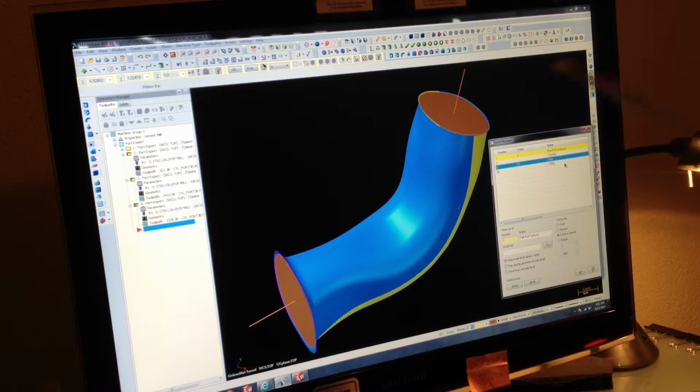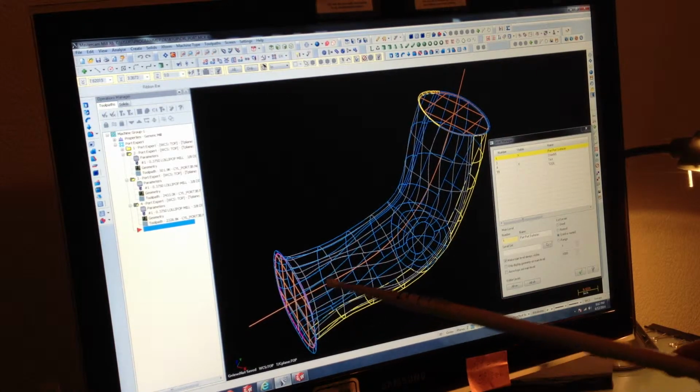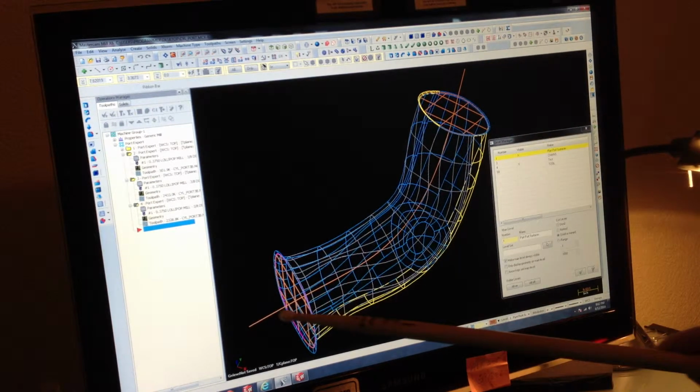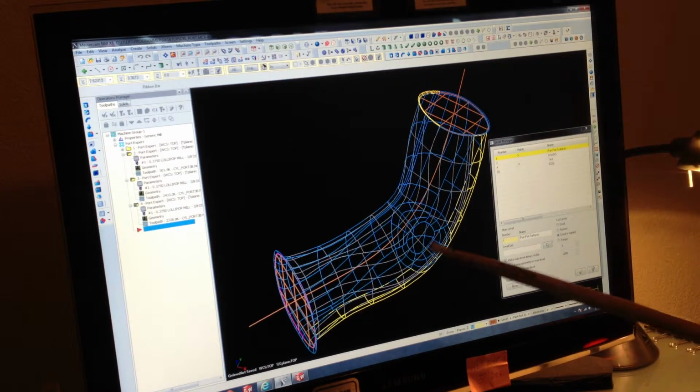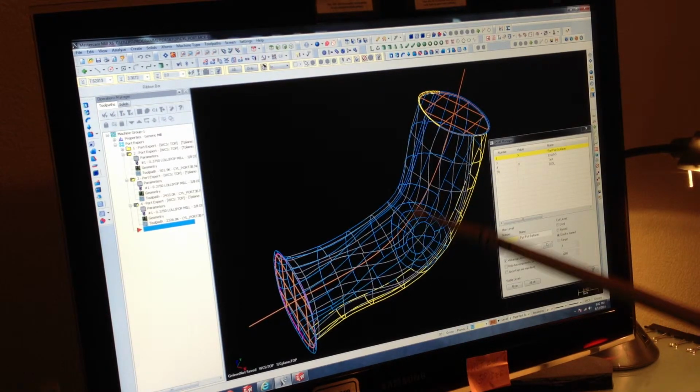Next thing we did, basically, we went out there and created vectors, 800 thousandths long each, and then we created a blended spline. I'm going to take the shading off, go to wireframe. Okay, so this is vector 1, 800 thousandths, and this is vector 2, 800 thousandths, and this is a blended spline, which is created in between these two vectors and from the surfaces to surfaces. And you can control the center of this spline. When you go create spline, there's going to be a small window on the left here, which controls the curve.